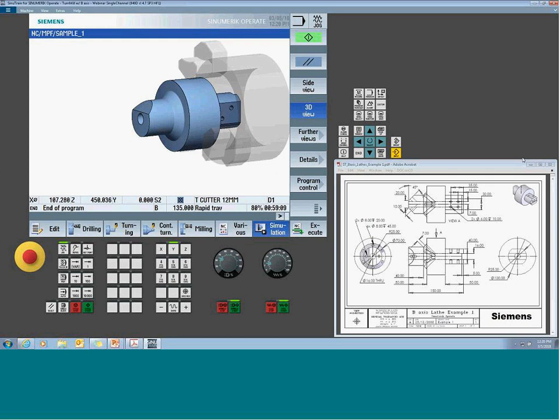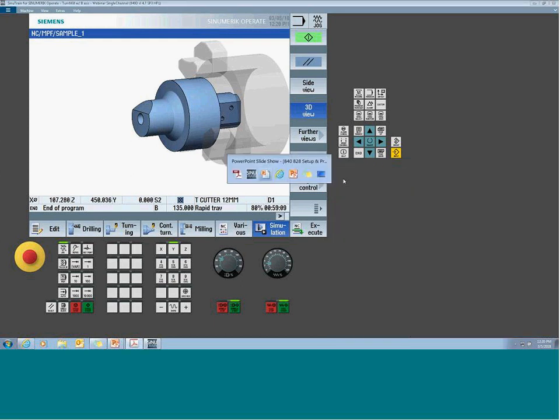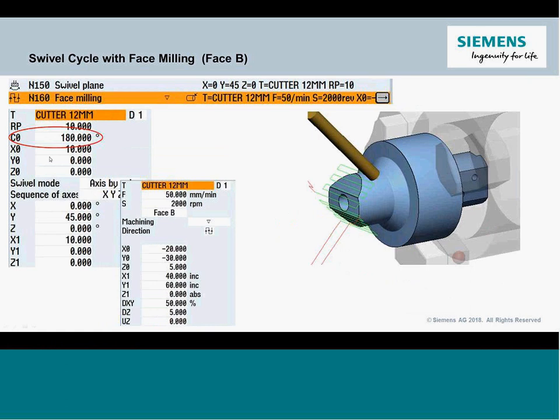Now we've got to get to the back side. I want to really just mimic that exact thing, but spin the coordinate system 180 degrees out. We're going to have to create a new plane, right? It's a swivel plane, and I'm just going to have a repeat of the same cycle. And that's what's going to spin it 180 degrees out for me. So I don't have to try to shift anything into the bottom. I can just pre-stage the part so it's sitting in a plus feature. Then I'm going to get my two flats.